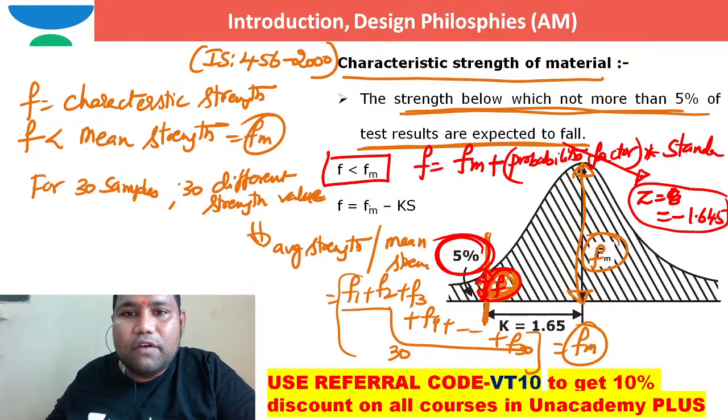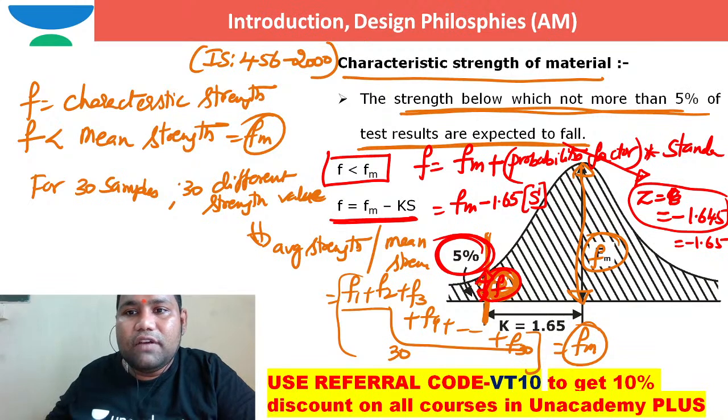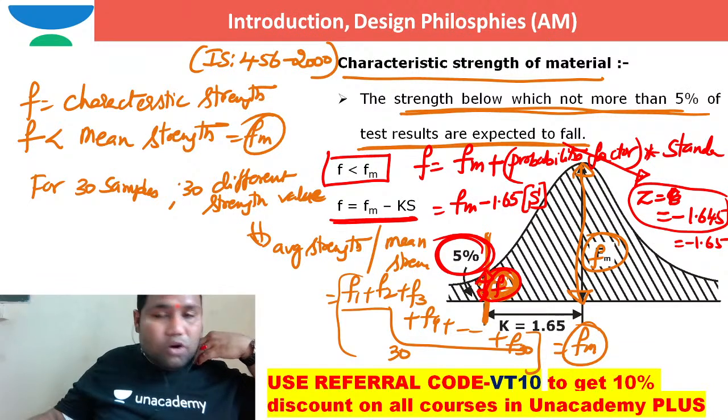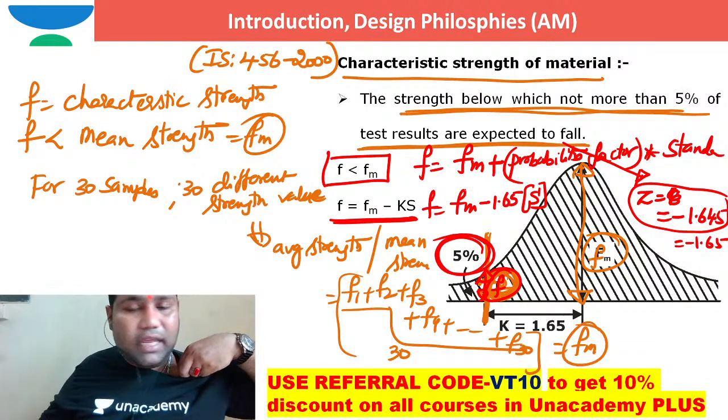That's the reason why they generally write f is equal to fm minus k into s, and the value of k is 1.65. So z is minus 1.645, and we call it minus 1.65 times the standard deviation. This is how we can work out the characteristic strength of the material.